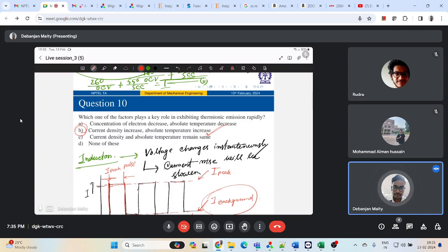And I told that with tungsten and carbon electrodes, the primary electrons carry most of the current, whereas for copper and aluminum electrodes, secondary electrons carry most of the current. It may depend on those work functions which I was talking about.